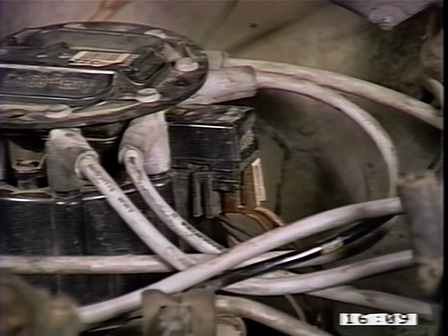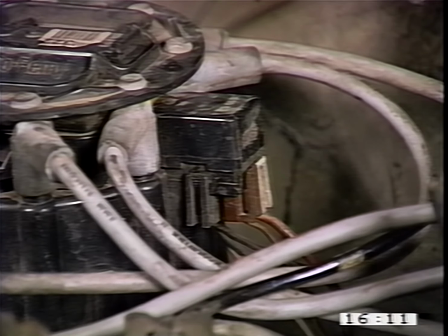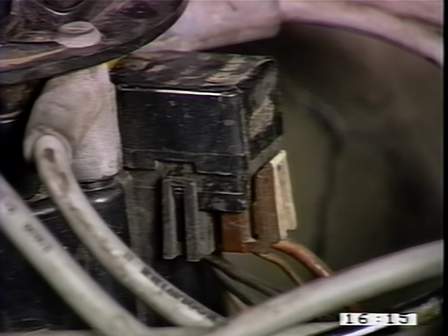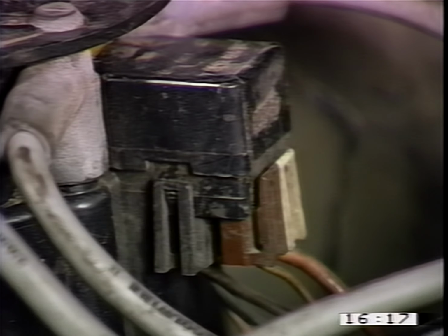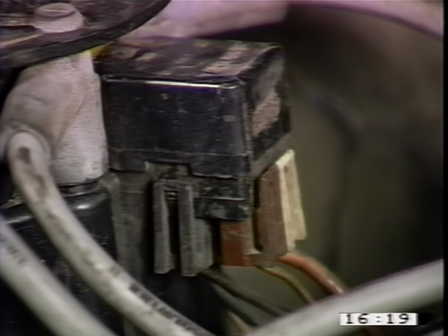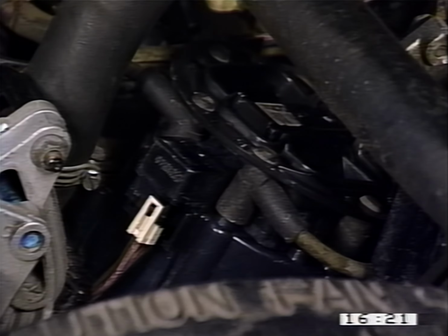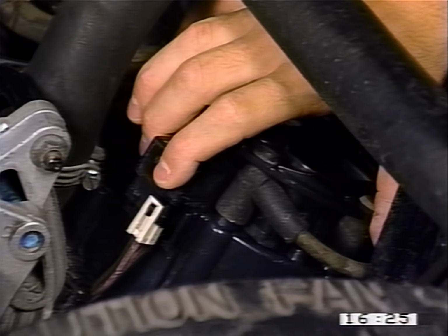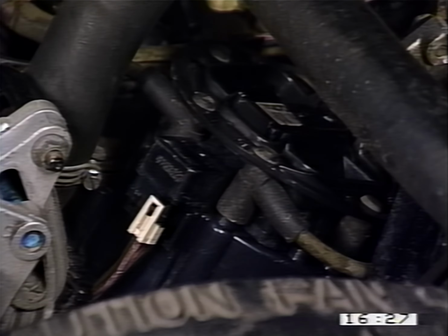This HEI reference EST return type of timing control is found on all GM C3 systems, from the earliest C3 HEI to the latest DIS C3I system. Since the TAC reference is so important, the ECM contains several diagnostic codes for this circuit. Reference signal problems are indicated by either a code 12, a no TAC reference situation with the ALDL grounded as mentioned earlier, or by a code 41.